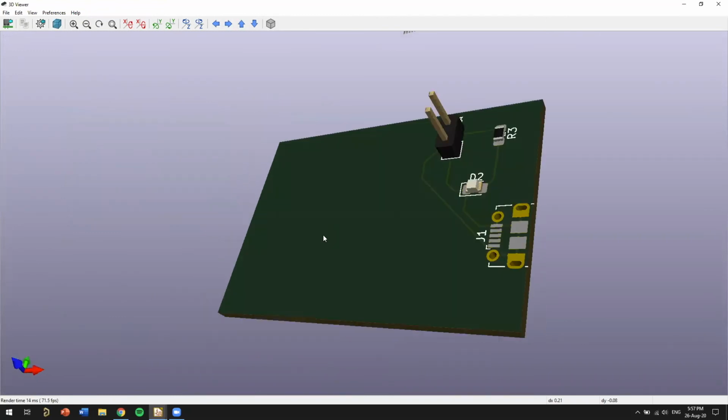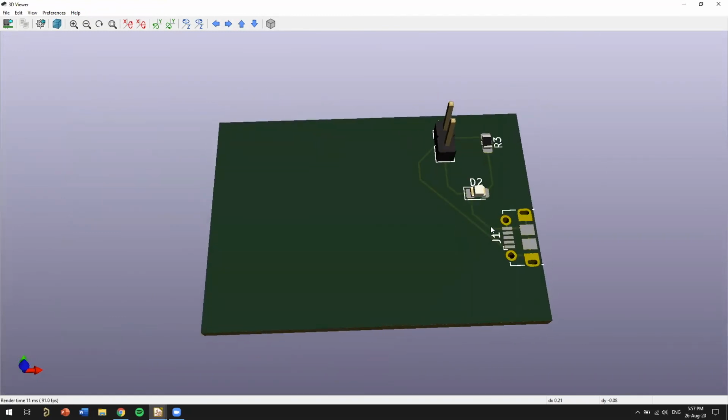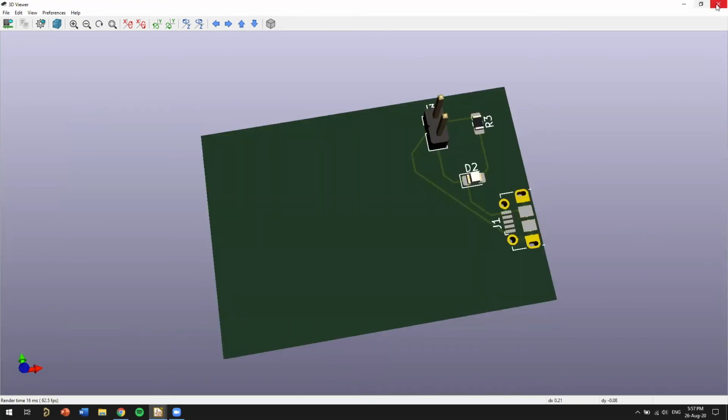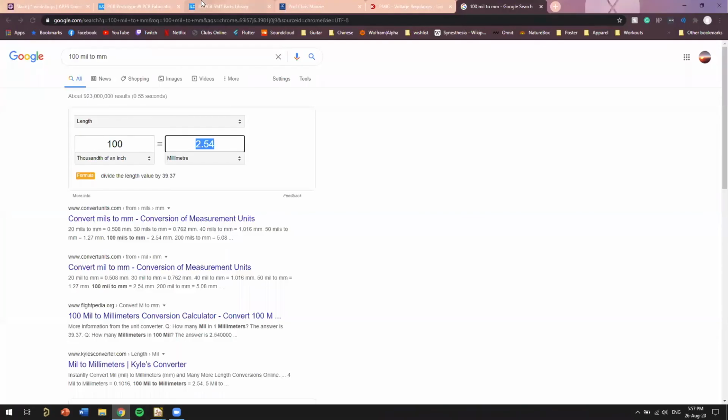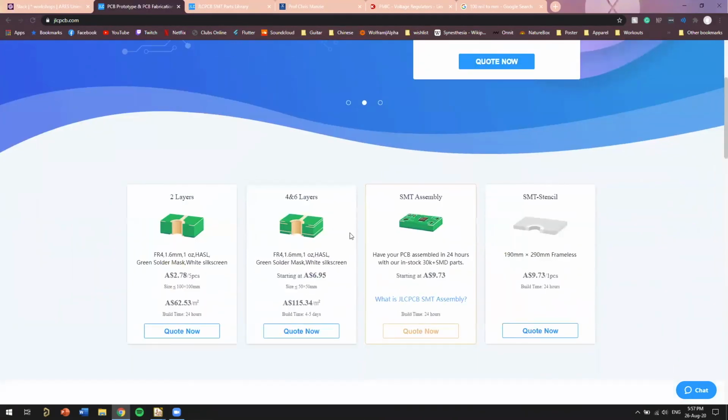And that basically summarizes the start of how you do this kind of PCB design. Once you have everything set up in here, then you can go on and create your manufacturing files, which is just a couple of clicks in KiCad, and then you can send it to, you know, JLC, and they'll assemble everything for you if you use their assembly service.